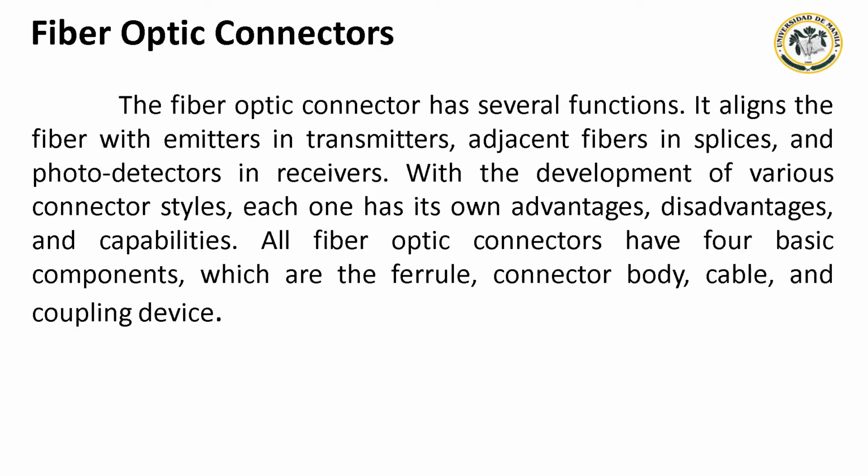Fiber optic connectors align two fibers end to end so precisely that light can travel from one fiber into another without bouncing off the interface and losing its signals. Besides, fiber optic connectors provide cross-connect and flexibility for the telecommunication network, so a complicated computer network could be modular and easy to manage.